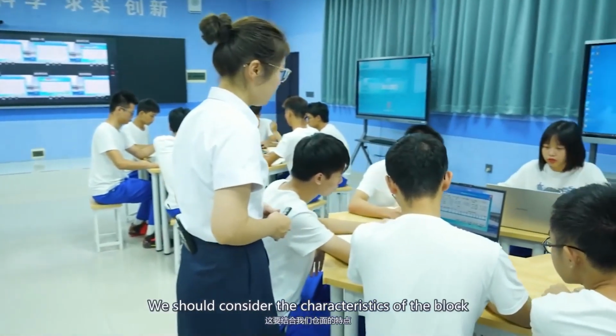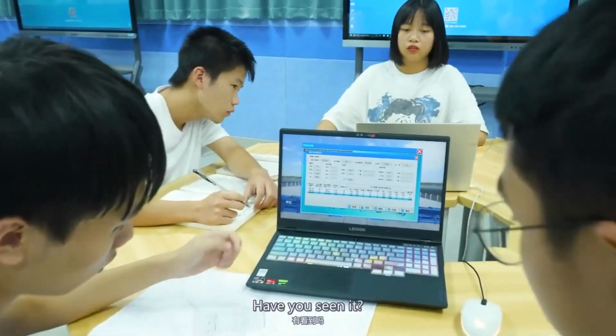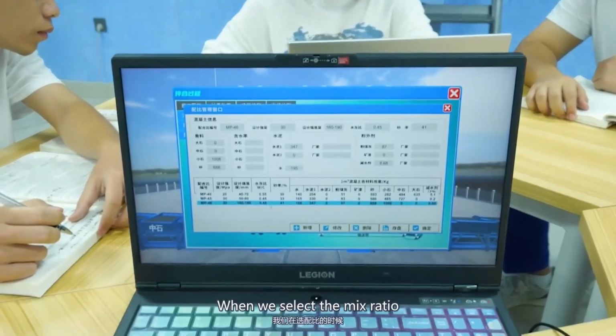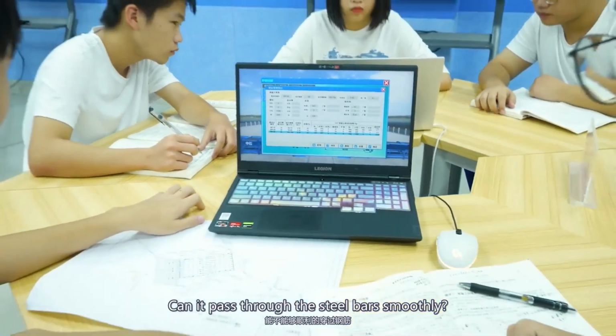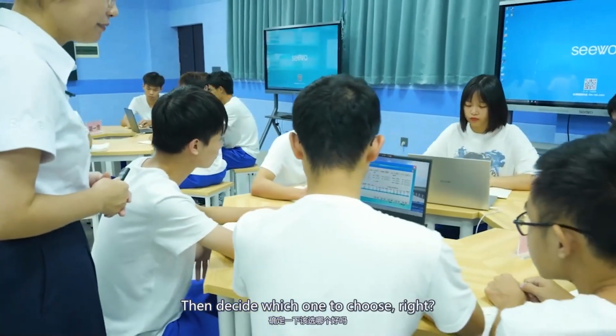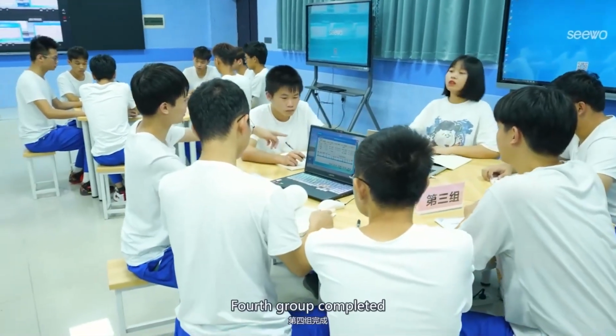We should consider the characteristics of the block. What is the spacing of our steel bars? Have you seen the drawing? On the drawing, it says 40 millimeters. When we select the mix ratio, we need to consider whether your aggregate can pass through the steel bars smoothly. Please check the specifications again, then decide which one to choose. Okay, I'll look up the specifications. Fourth group completed.